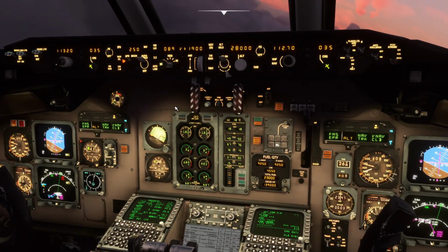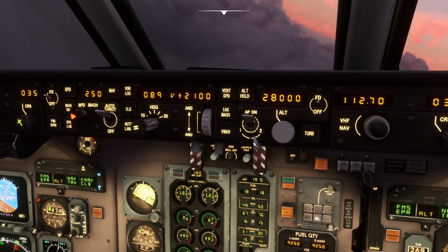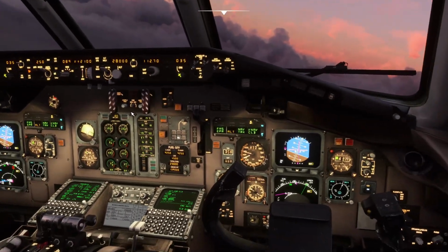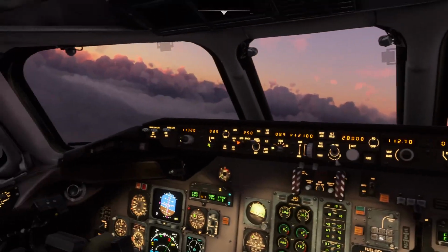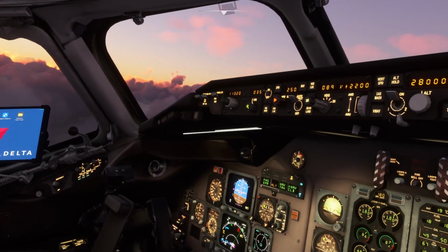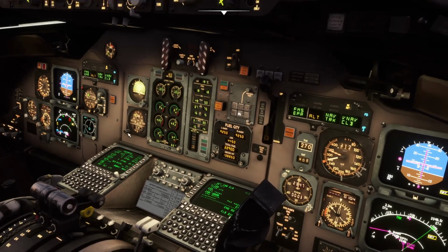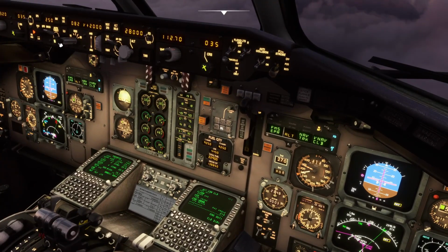One thing I just did there that I didn't describe is this. So this changes the autopilot source. So if you're the first officer and you want to fly the ILS displayed on here, you need this to be on AP2, so it'll follow this radio tuner selector thing. So that's good. We're making all these restrictions here. Herbie at or above 4,000 is the only main restriction. I'm pretty sure we did that.